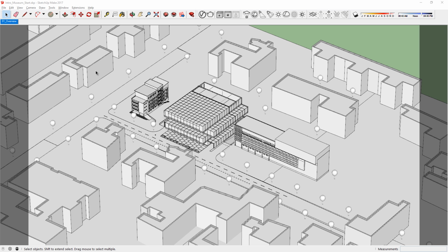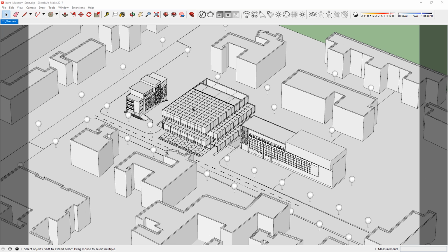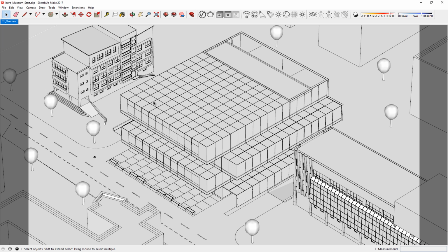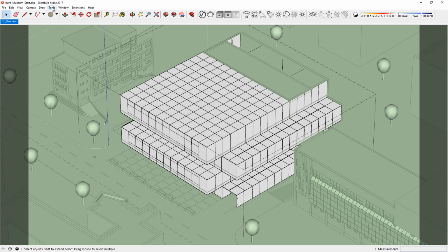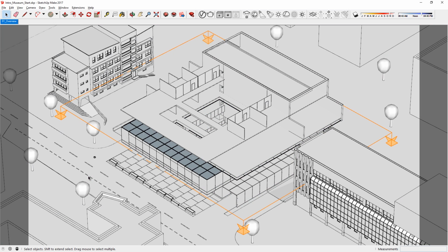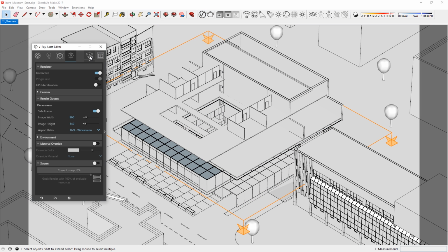Continuing with geometry optimizations, another big one is the clipper. The V-Ray clipper is very much like the SketchUp section plane. It basically allows us to cut through geometry without destroying it. This way we can achieve more artistic views or just see what's going on inside. By default, even when you create a SketchUp section plane, it will be read as a V-Ray clipper. Let's do that. I'm putting this one in a group because I wanted to cut only through the glass. Okay, random.